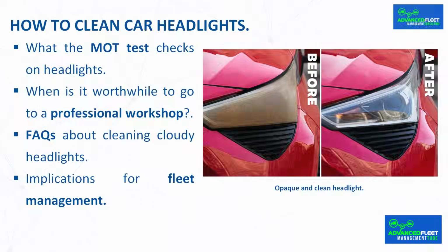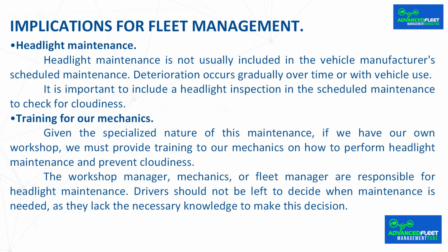Implications for fleet management? The main consequence of a headlight becoming cloudy is a loss of luminosity, increasing the risk of accidents at night. The following measures are recommended. Headlight maintenance. Headlight maintenance is not usually included in the vehicle manufacturer's scheduled maintenance. Deterioration occurs gradually over time or with vehicle use. It is important to include a headlight inspection in the scheduled maintenance to check for cloudiness.